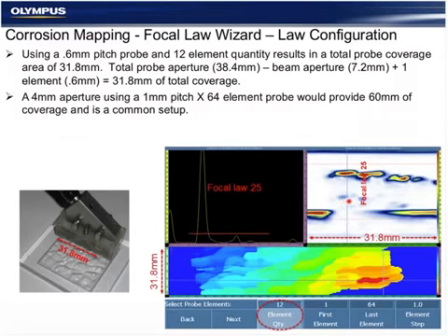every A-scan summed. As I move this blue cursor here, I can see the A-scan that generated that data point with a 1-element step resolution. When the step resolution is increased to 2, the data file is 1/2 the size. The acquisition speed of the scanner is double, although we don't typically consider this application a speed application that would push the limits of the PRF, like multi-group weld inspection.